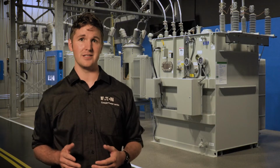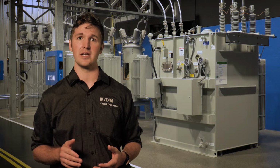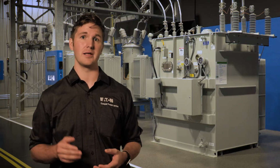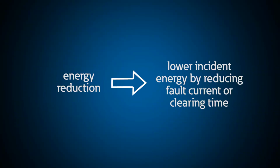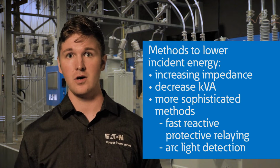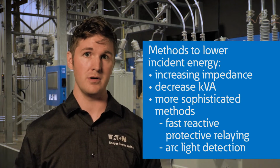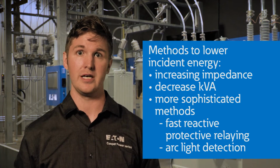The commonality in these designs is they create a way to access key maintenance or operation devices within the transformer without entering the main enclosure and arc flash hazard zone, thereby limiting the risk of the arc flash events occurring. Energy reduction, on the other hand, involves lowering the incident energy by reducing the available fault current or the clearing time if a fault were to occur. This can be done by raising the impedance, lowering the kVA, or via more sophisticated methods. For example, fast reacting protective relaying or arc light detection can de-energize the transformer quickly in the event of a fault. In any event, all arc flash energy reduction methods aim to lower the incident energy at the transformer output, typically the low voltage terminals.